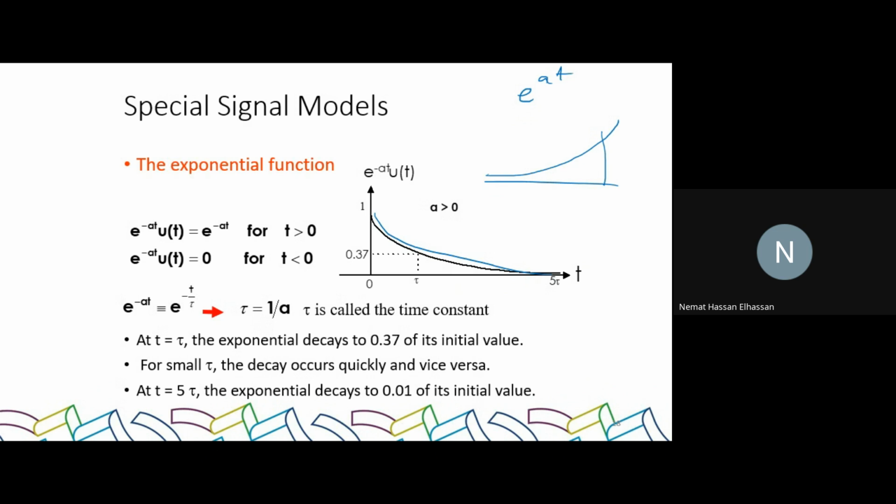This could remind you of the exponential growth of charge in a capacitor and discharge in a capacitor. Now, generally, when we're talking about an exponential growth, we always refer to the term tau, where tau is a time constant. We'd say that at 5 tau, we assume that either the signal reached its maximum value or the signal reached its minimum value of 0. What is tau?